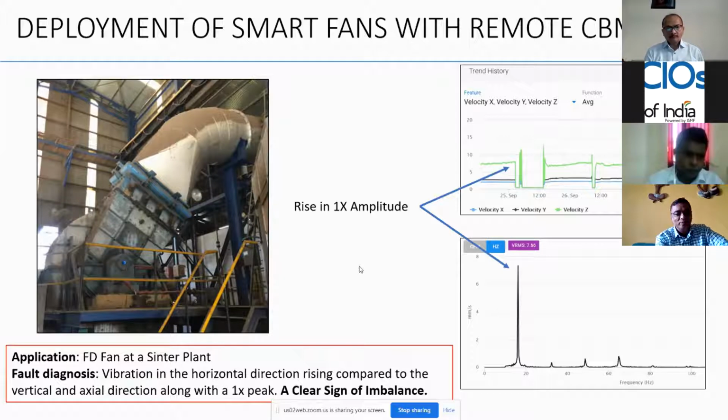In discrete manufacturing, in metal cutting operations, when you're monitoring the spindle condition and you know the load of the spindle based on the vibration data, you can actually improve the cycle time. So you can make more parts in the same amount of time, which will improve your throughput. So it can impact availability directly and throughput indirectly.